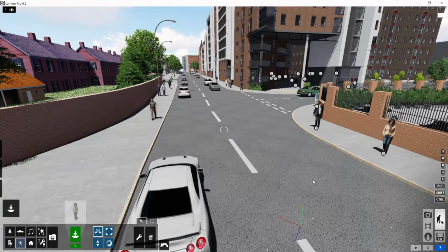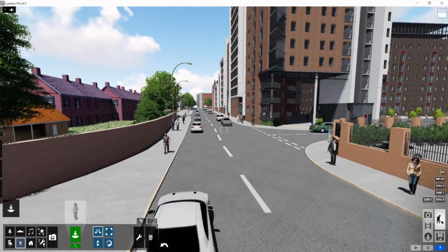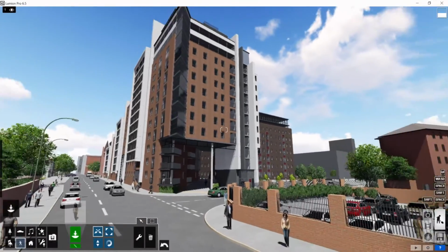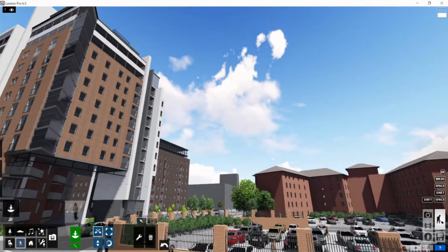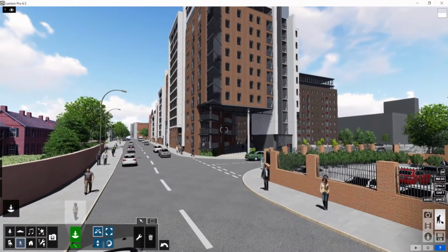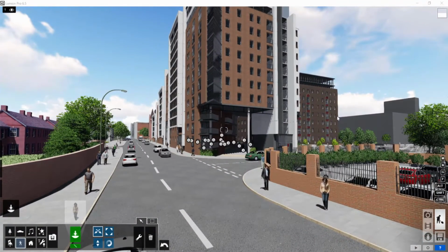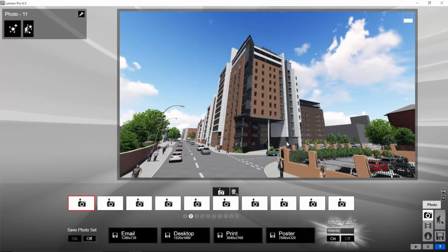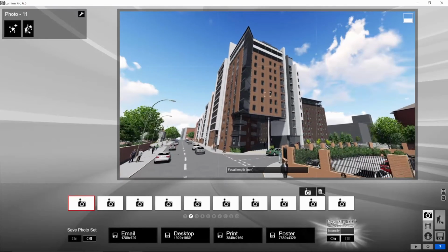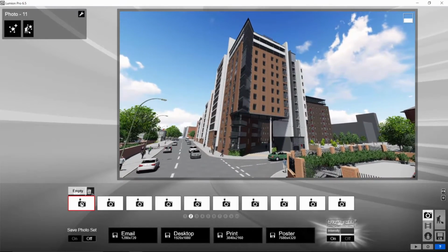People have now been added to the scene, and if I pan around now, you can see the change in our scene from importing the CAD model to this point. Very simple processes. And now at the stage where I can look towards producing some rendered output. The first thing I'll do is head over to camera, which is where we produce our stills. Navigate to your desired viewpoint, and then capture. We'll go to one more.